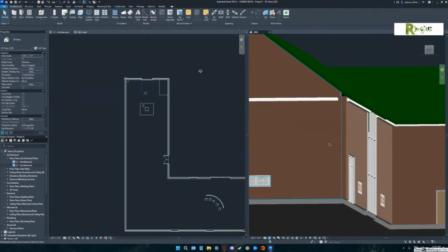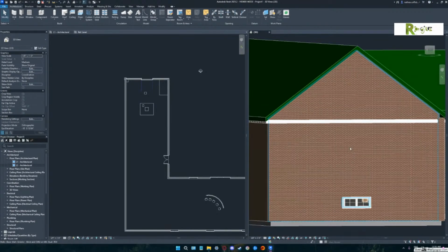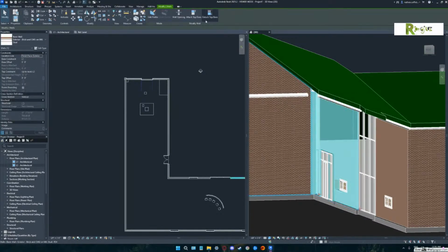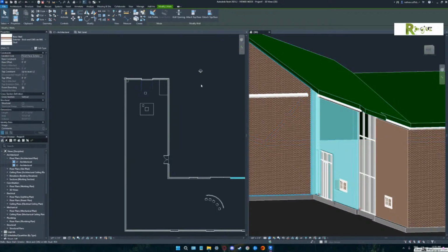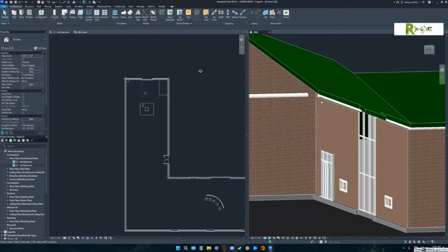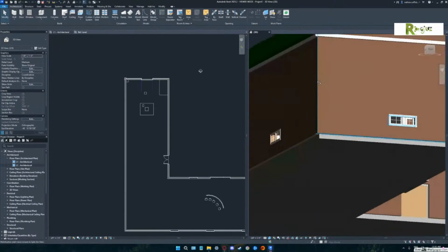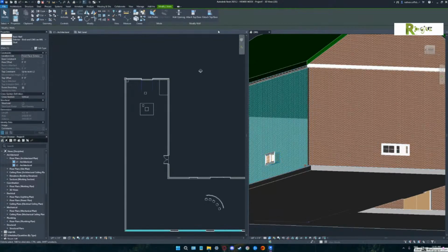Now you do see how that wall right there is not cleaning up. You would want to attach that wall to the roof as well, where that little notch of the corner is coming out. Oh, right here? Right there, yeah. Because basically what that's saying is it's just not healing that wall to that roof. Okay. And that's how you're going to deal with all kinds of more intricate detail when you're getting into the roof situations. I got you. And then does that do that to every wall? Yeah.